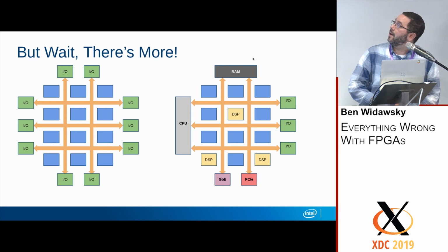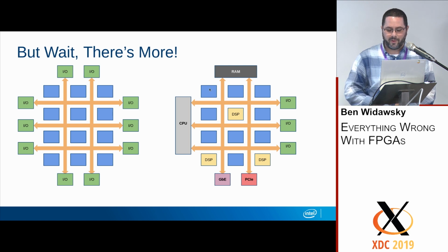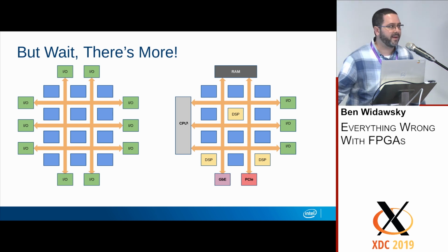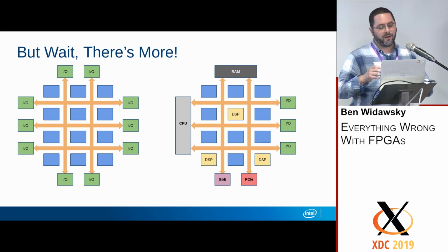And you might have memories, typically each of the LUTs. I want to hand wave a little bit because it's not worth the details, but you might have some memory and DSPs and so on. And so a lot of these higher-end FPGAs will combine all these hard IPs in addition to having the programmability.